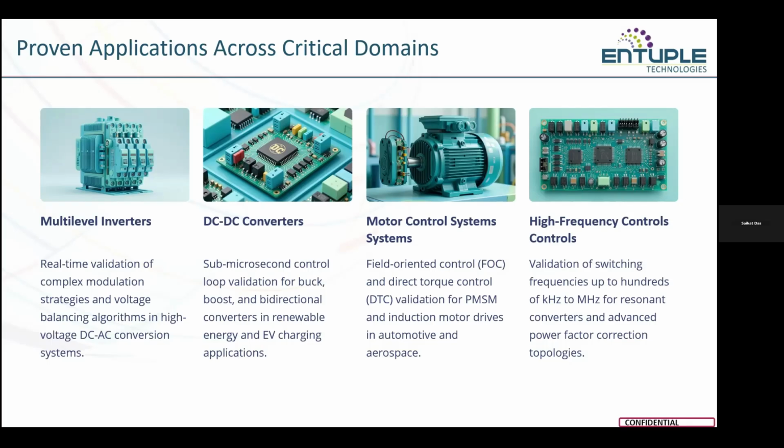Finally, in high frequency control applications, we validate switching frequencies ranging from hundreds of kilohertz to megahertz, for resonant converters or advanced power conversion topologies. Across all the domains, the common requirement is deterministic real-time behavior and safe validation. That's what makes RCP a proven solution for complex mission critical control systems.